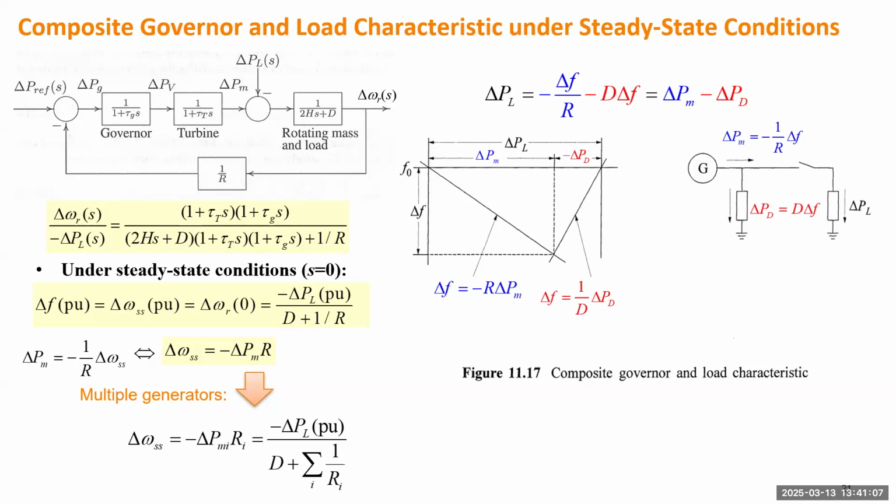All right. So this one is plain. When you have a load change, the load change is estimated based on the original frequency. But once that load change is added to the system, the frequency will change. Because of the frequency change, the remaining load will not be exactly the same as the original load because they're operating at a different frequency. So what the remaining load appears will be slightly different. And also your generation needs to be changed due to the governor. So in order to have the power balance, finally, the change will be reflected on both the generation and also the frequency sensitive load. And they together determine the frequency deviation.